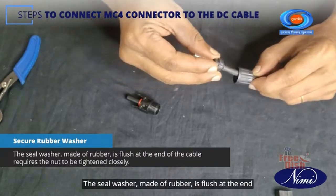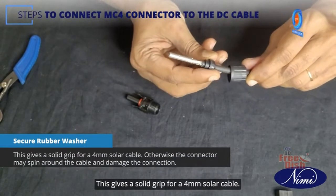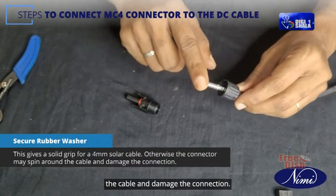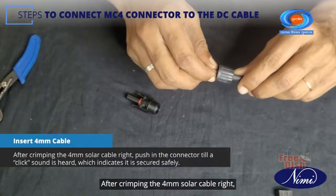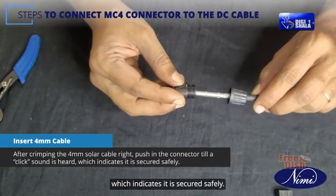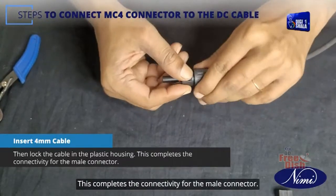The seal washer, made of rubber, is flush at the end of the cable, and requires the nut to be tightened closely. This gives a solid grip for a 4 mm solar cable. Otherwise, the connector may spin around the cable and damage the connection. Insert 4 mm cable. After crimping the 4 mm solar cable right, push in the connector till a click sound is heard, which indicates it is secured safely. Then lock the cable in the plastic housing. This completes the connectivity for the male connector.